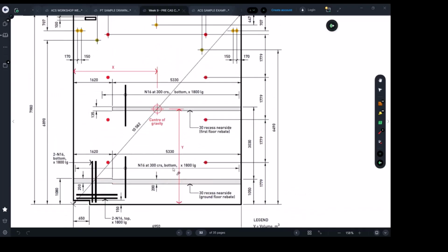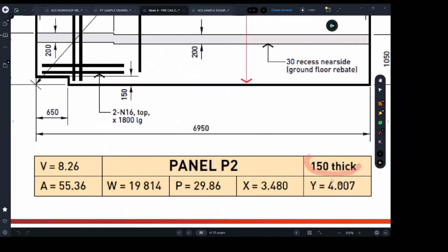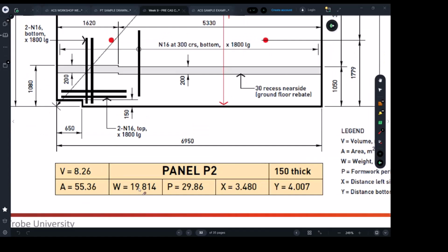So what I'm trying to say is these shop drawings will give you more information about the thickness, and ideally they all should be like this. Also, the concrete strength should be written somewhere. And now this one talks about the weight, which I was coming to, the weight of the panels. That's nothing to do with the engineer or the architect. You are the construction engineer.